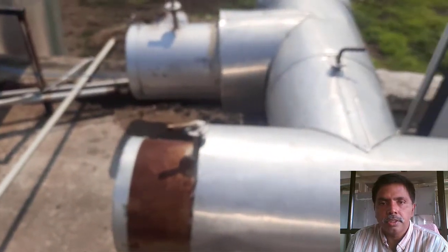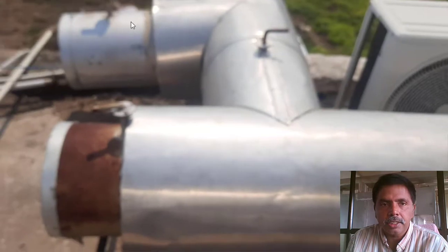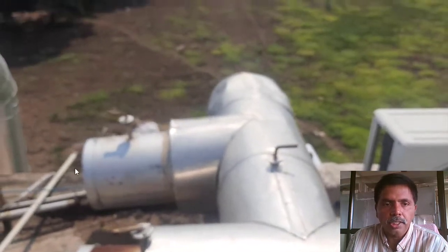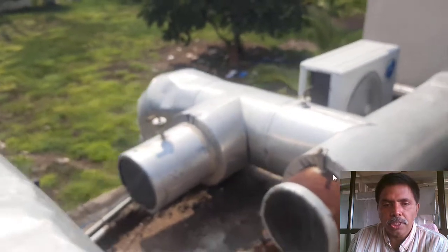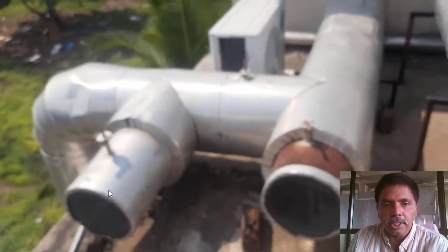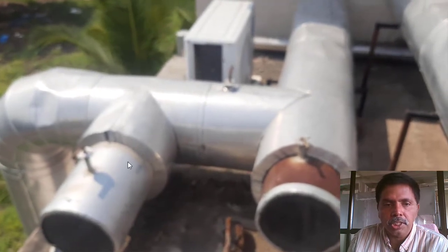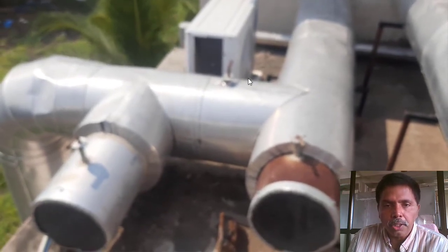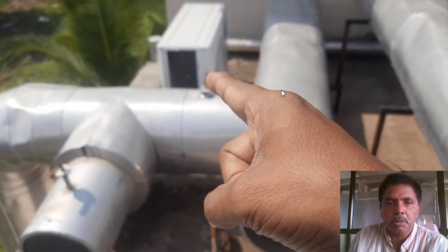It is going from the dryer. It is coming in this direction. This is dryer outlet and blower inlet. This one blower inlet, this one dryer outlet. If bonded moisture we are removing, simply we will close these inlet and outlet valves and we will open this damper. Automatically recirculation of the air will take place.